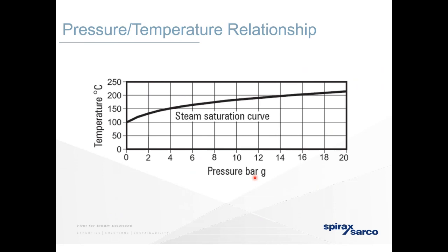2,706 kilojoules per kilogram. This information, together with the enthalpy of both steam and water, can be found in the steam tables, and this allows us to work out how much energy, how much temperature we need at the end of our line. On the table in front of you, water exists below the line, and steam is on and above the line. Superheated steam would be the higher you get above the line.